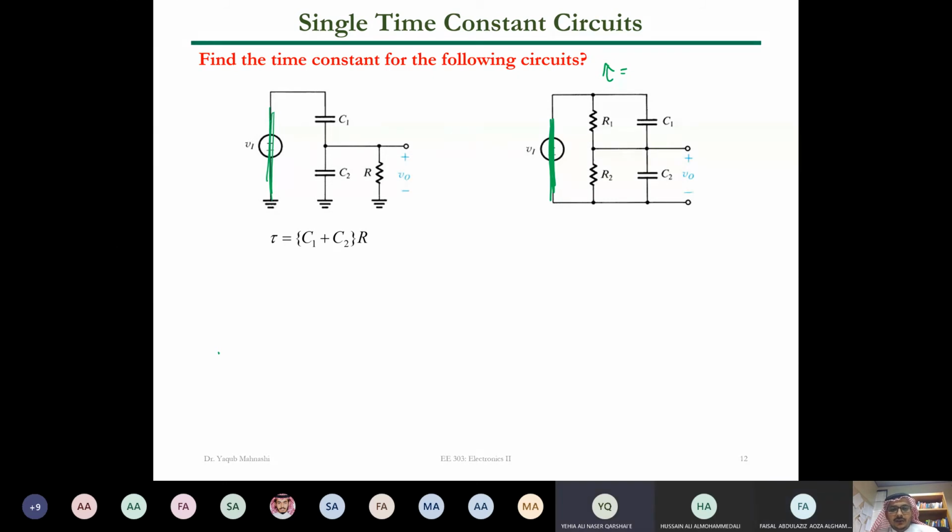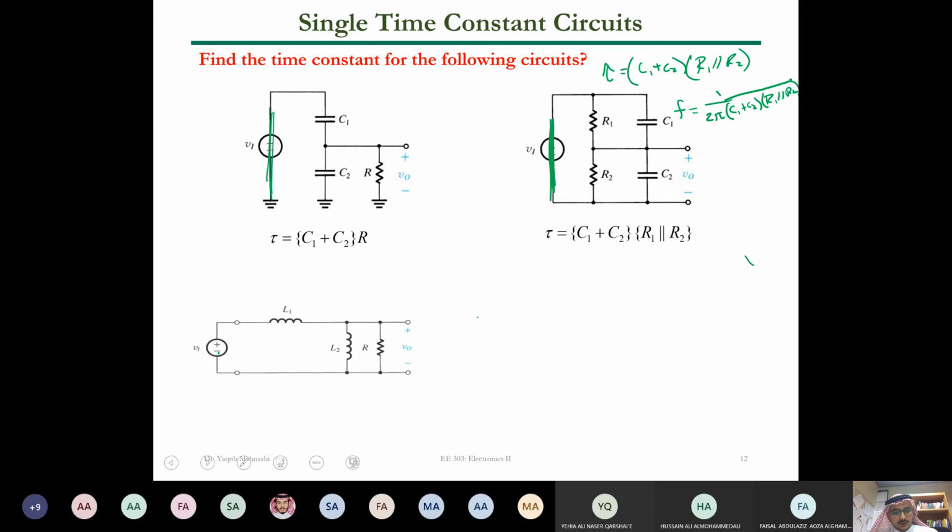So in this system, actually we have only one pole. So C1 will be in parallel with C2, which is C1 plus C2, right? And then both of them will be in parallel with R1 and R2. And the corner frequency or the pole of the system will be seen at this frequency, C1 plus C2 with R1 parallel R2. Okay. We are now building knowledge here to understand how to find the poles and zeros.